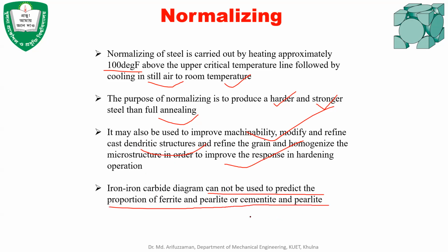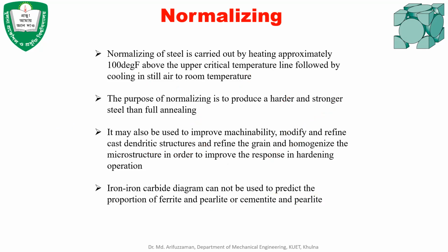Since the cooling rate is high, you cannot use the iron carbide diagram to predict properties. You have to analyze the microstructure and then quantify.